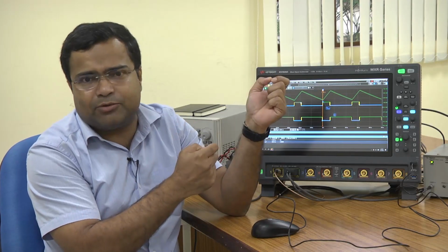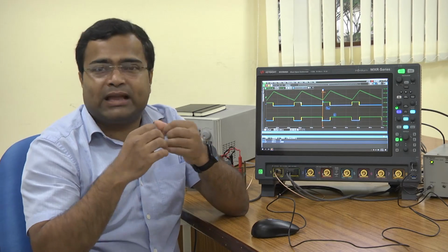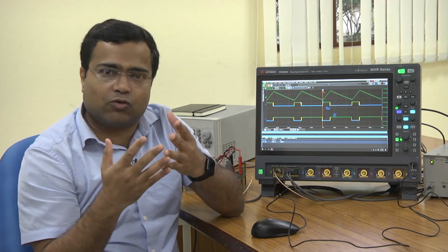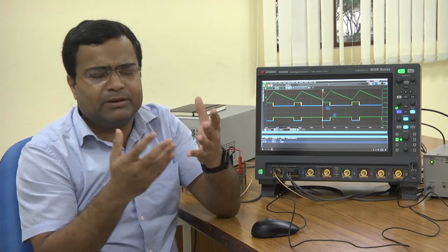because you want to debug a lot of things. In the FPGA, what I have started demonstrating, and I will be demonstrating more in videos, we can check, because if you encounter some problem in the digital code, you want to debug it. So that means you have to pass some of the digital signals through your IO pin, and these digital signals are logic signals which only take 0 and 1. So you can take such multiple digital signals.